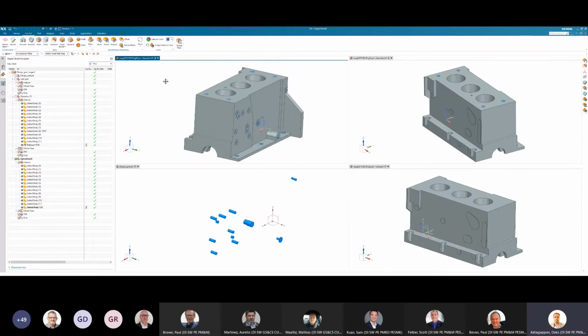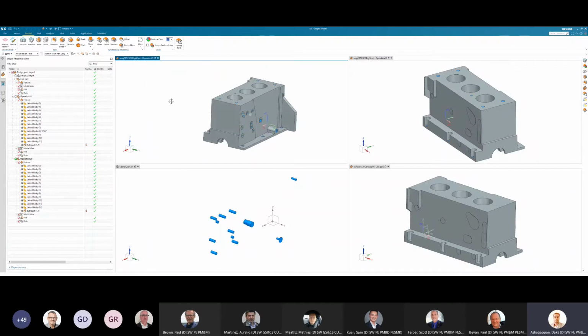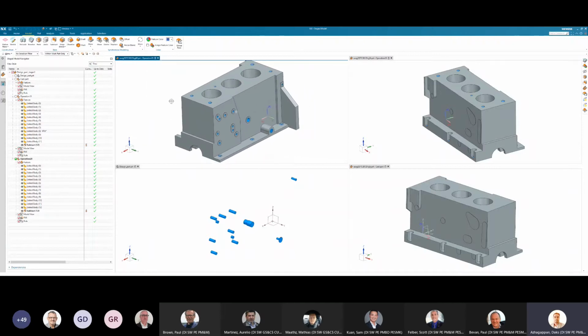But what we have done is we simplified the whole process of building the stages, accessing information from different stages, and of course you can start working on the shapes you're going to build. So in this case, I'm going to simply select my tool bodies, and then select all those. Select the target and the tool bodies and build my shapes. So this is how you could build different operations actually, right?